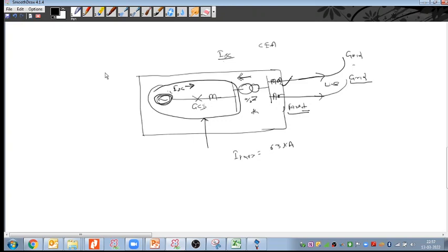Suppose we consider a wind farm from this side. They will consider feeder wise, right? I think they will calculate for a feeder, say 25 megawatt or 10 megawatt per feeder. So they will consider the 10 megawatt of power for the short circuit calculation, right? Yes, right, Ganesh. In your case I am confident this is right. We take feeder wise.